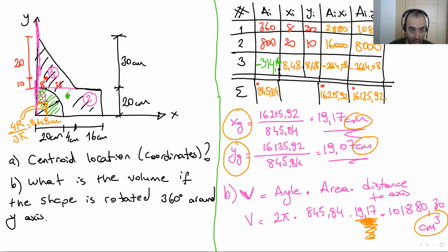I don't know where it is, but it's G. Now this distance is, according to our calculation, this one, right? Now this point is our center of gravity point. While we are doing a volume calculation, we use the distance from this point. So now we have the total shape, its center point is here.